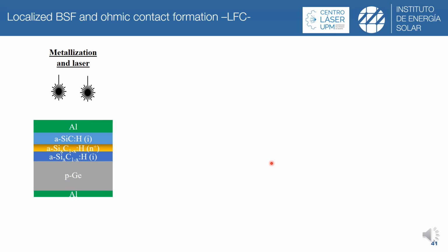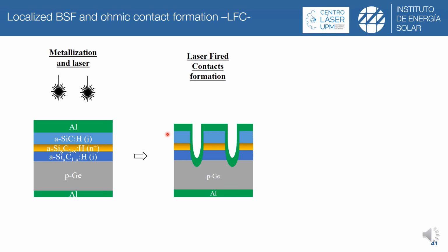In this technique, laser firing of a metallic layer provides opening of the dielectric layer simultaneously, without diffusion, creating all-doped regions in a localized pattern. Note that the n-type doped amorphous silicon carbide layer, which is used as a doping source, has been kept in order to analyze if overcompensation of n-type dopants can be achieved by aluminum diffusion during the laser-fired contact method.